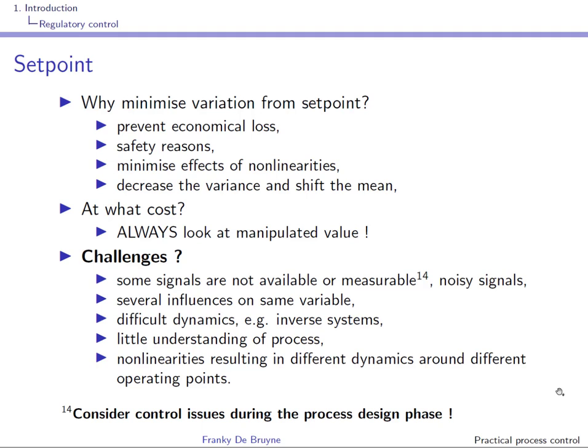There are of course quite a few challenges associated with process control. Some PVs are not available for measurement because of the cost of the sensor, or because technology does not offer a sensing solution. Sometimes soft sensors, for instance observer-based sensors, can offer a solution, and this should ring a bell for control engineering students, as we have tackled this in the course of state space control.